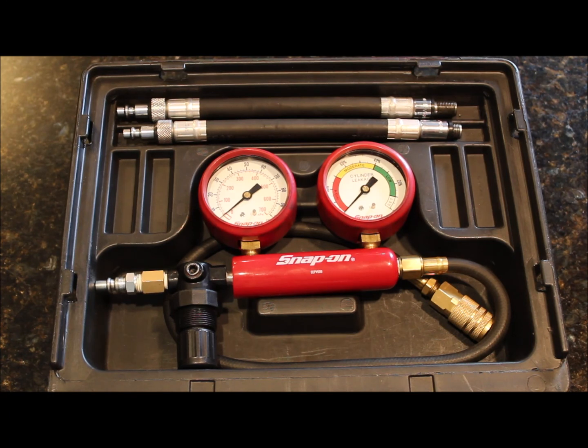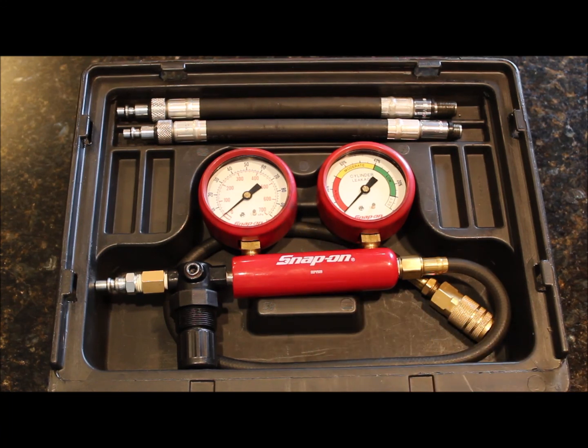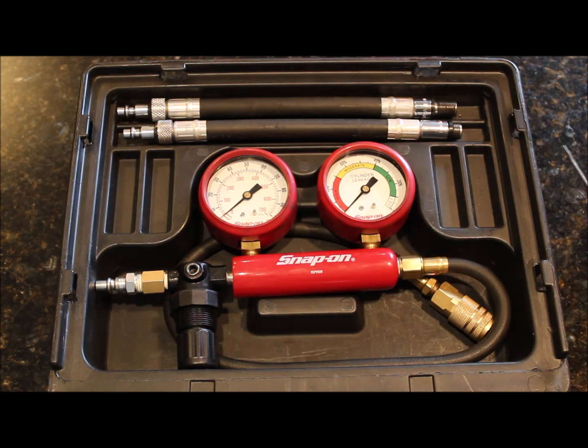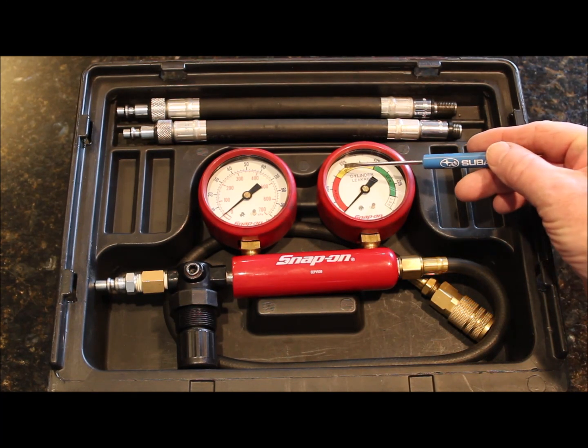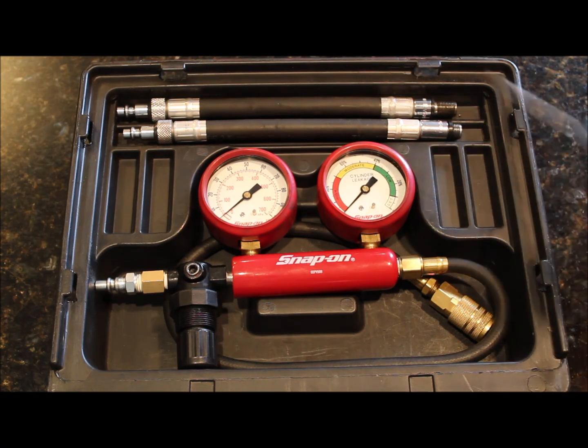So back to the bit about the small engine. Sometimes 100 psi is too much, and so the piston gets pushed down. If that happens and there's no way to lock the crankshaft, what you may have to do is set your input gauge to 50 psi, and that means everything's cut in half on the other side. So zero leakage would then be 50 on the output side, right? And if you had 45, that would be 10% leakage.